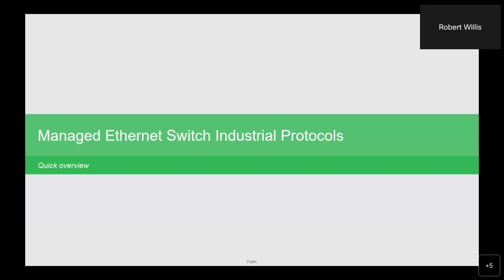So how do we get in? Today, we're going to talk about the protocols. When I get into the actual switch, I'll go through some of the other screens. So how do we take our Modicon switches and allow you to bring the data from the switch into, say, a Modicon M580, into a SCADA system such as a Viva system platform, or another SCADA system using Modbus TCP IP or Ethernet IP protocol?